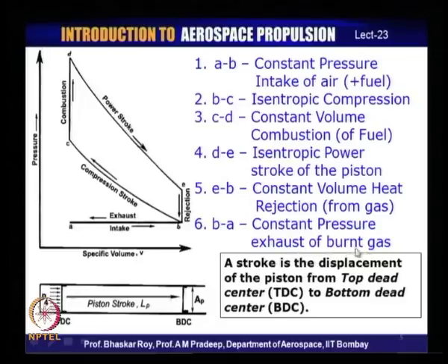So, this exhaust of the burnt gas starts happening as the piston head starts moving, and this burnt gas is exhaled out of a port here. The port is timed to open at this point of time, and this burnt gas goes out through this port outside the system, and then the fresh charge or fresh air starts coming into the body of the cylinder.